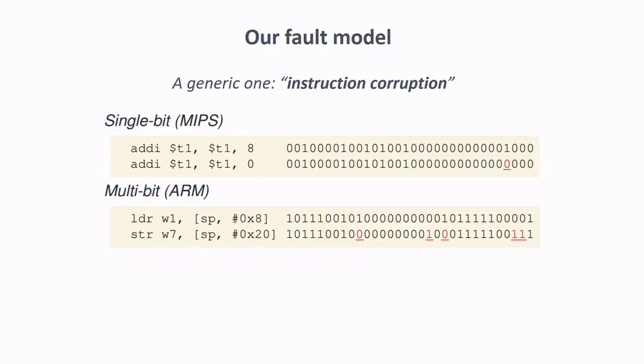So if in our attack we are able to flip that bit, then the instruction which is executed actually changes. Of course, we cannot control how many bits are flipped. So even in the case of ARM, it might be possible that multiple bits are flipped, and instead of having a modification on the operand, you actually change the instruction. So instead of having a load, it will turn into a store. Again, we don't know, but in our modeling, we think that these things may happen.